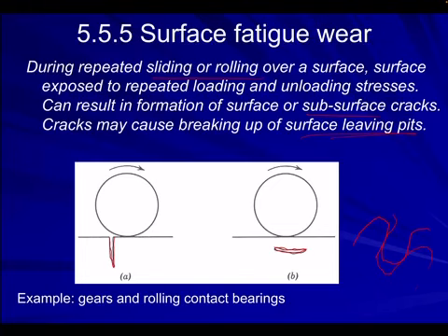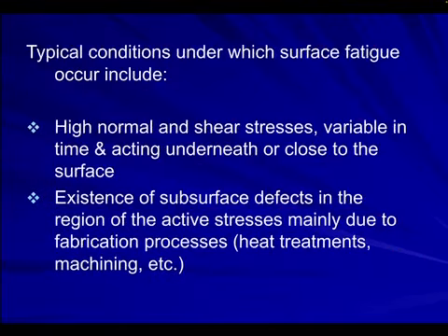So as the gears are moving, you're going to get very high compressive stresses, which will also cause shear stresses below the contact point, and that's going to give you cracking.